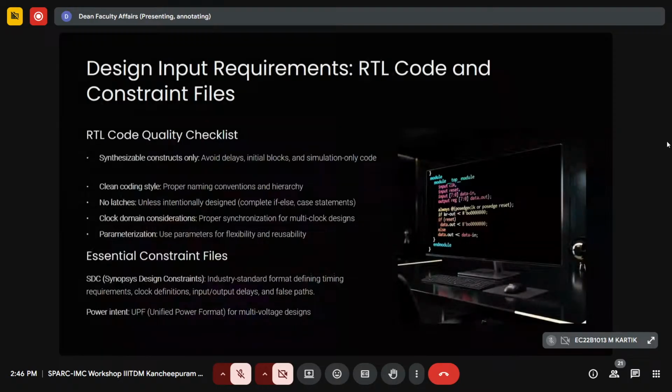So latch timing analysis is very complex in industry. That's why we avoid latches, though they are preferred for some multi-clock domains. We use latches in clock gating and so on, which I'll explain later. But generally, as a replacement for the flop, we don't use latches. For now, understand that there is a timing analysis complexity, so you don't use latches.